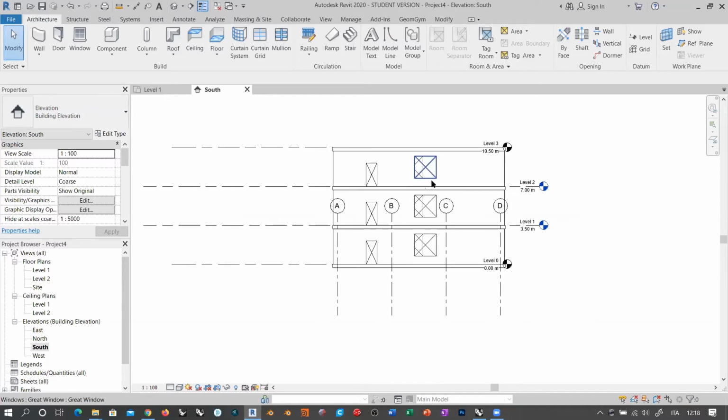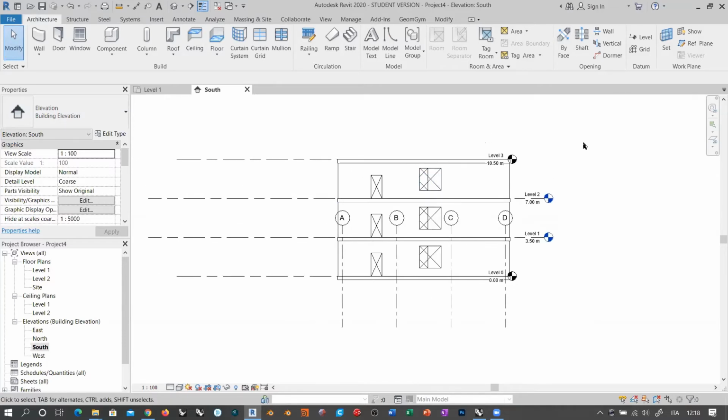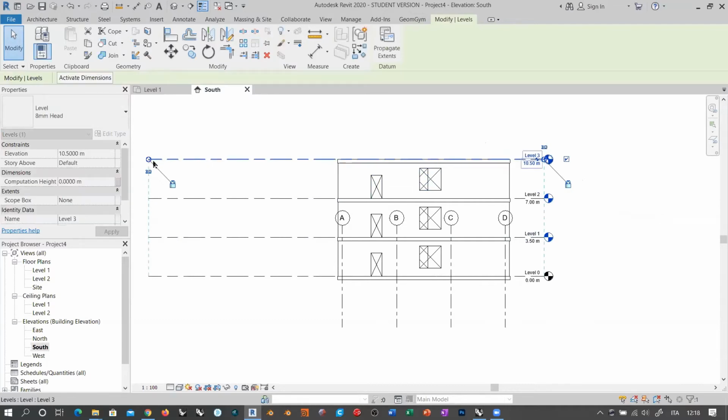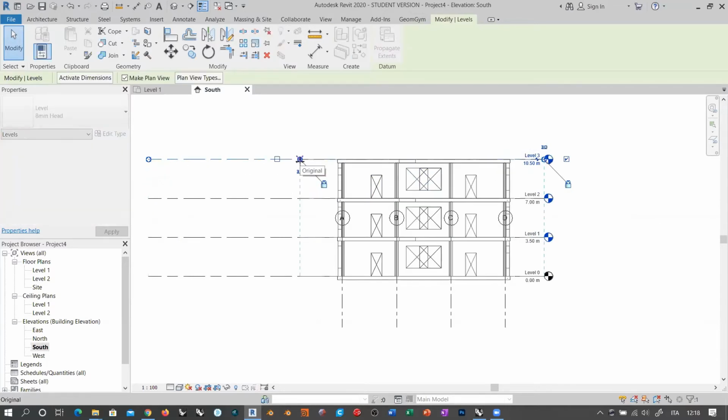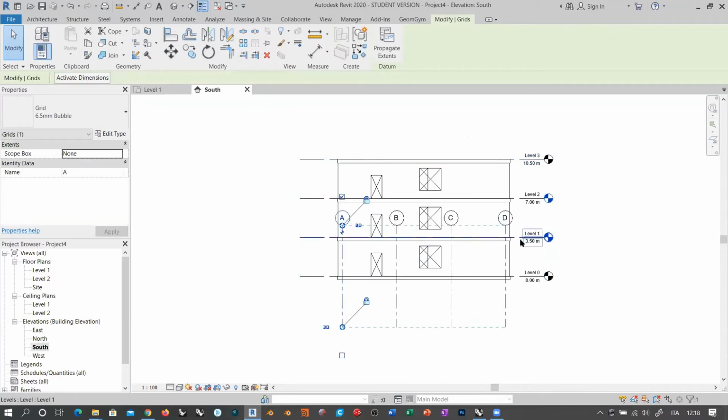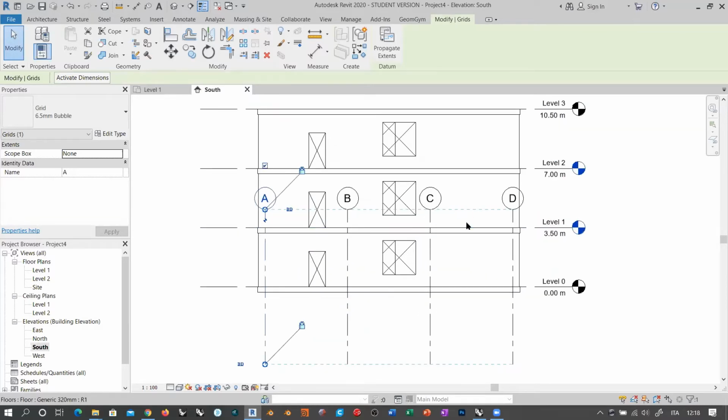So the first thing that you might want to do when you import something from Rhino to Revit, in order to keep things neat and organized, is to align levels, because this is something that visually helps a lot. Okay, so you see that they must be aligned in both extensions, and therefore you can now move them all together. See, also the sections, they are not defined vertically, so there is an attempt to cover the project, but this is only referring to the first two floors, which were already present.